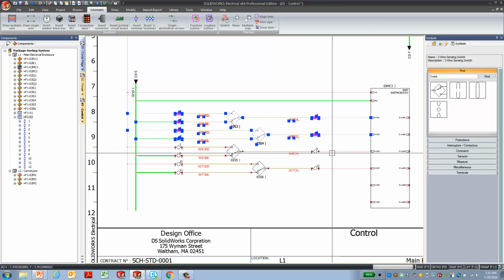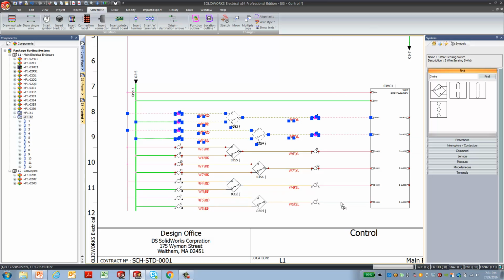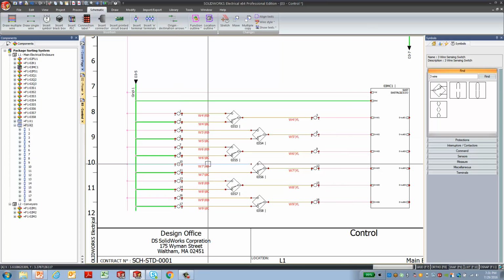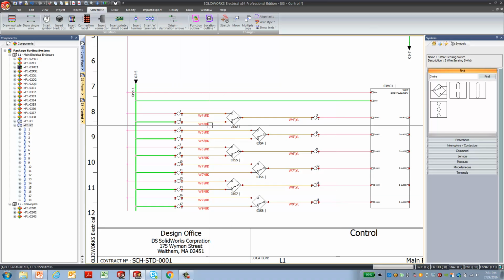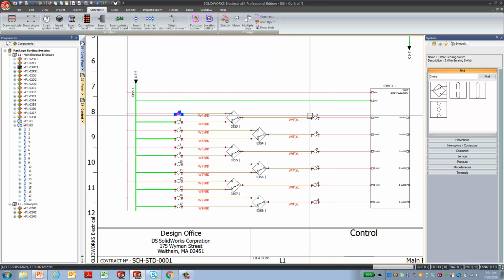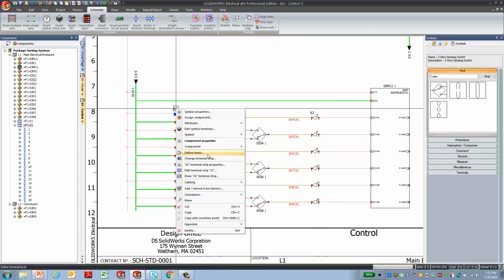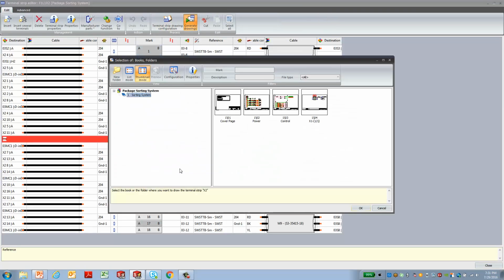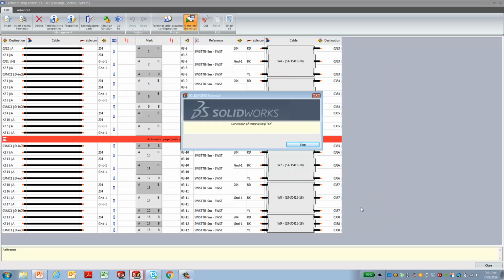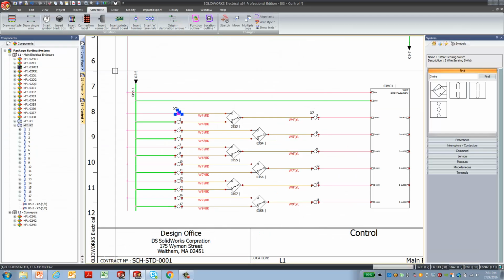And we'll just grab that pair now and just copy that down. And since everything's staggered, everything spaces out correctly. And we've just added, as you can see, 6 new cables, 18 new terminals, and this new strip X2. So let's show that. And in fact, we'll go back and edit X2, and we'll go ahead and create a drawing. And we'll take a look at that drawing.